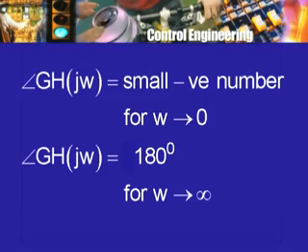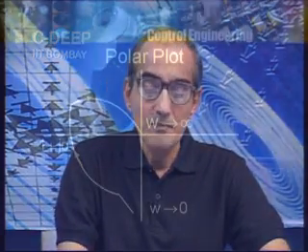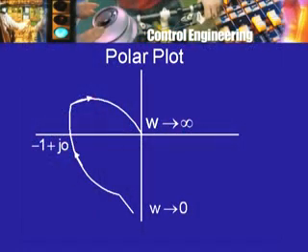Now, that is a numerical computation which one can do, and of course, in practice one does choose different values of omega and gets the value of omega close enough to the value where the phase shift will be exactly 180 degrees. Knowing that value of omega, we can calculate the gain by maybe calculating the lengths of the various vectors, or by evaluating GH j omega as a complex number by doing complex arithmetic on the calculator or with a program. It does not matter what you do. So, qualitatively this is okay, but we may need this information, and for that we will have to do some calculation. So, it is not that no calculations are required at all, but qualitatively we know what is going to happen.